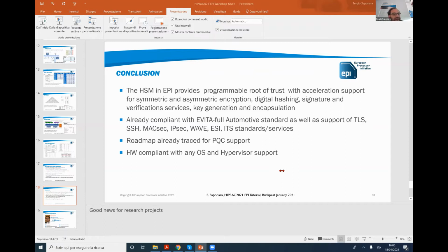In EPI2, for example, is foreseen a work dedicated on giving security on RISC-V. So here, the use of RISC-V is we can substitute the RISC-V, for example, with the Cortex-M, a not so complex processor like another ARM, having a diversity, since if we are giving the security on an ARM-based system, it's better not to have ARM in the IP. In order to give a certain programmability, the RISC-V was selected. But here, for the moment, the RISC-V is the Ariane IP, giving a sort of computation programmability.